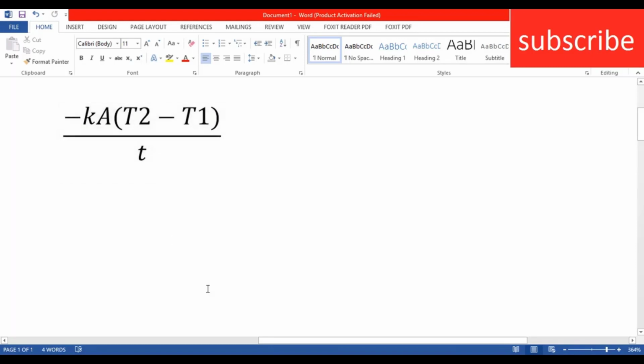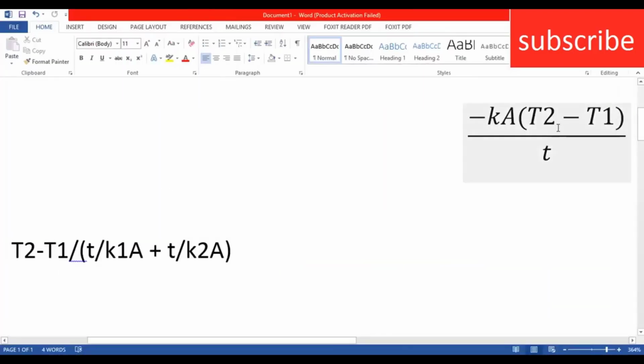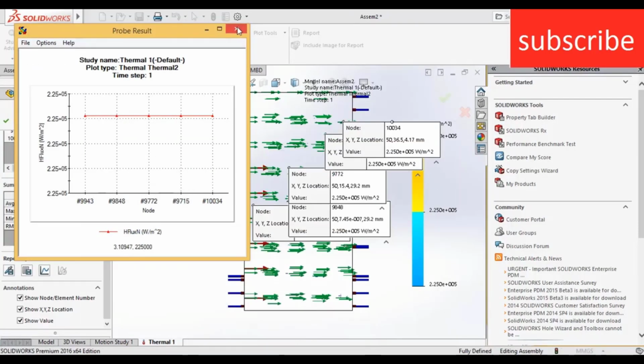If you put in the values of all the things we calculate, for example, K is 50, I guess, the material value is 50, and area is 100 by 100 mm. So you need to convert the units. Either you convert A into meters, so that T in meters you can calculate it, because our units here are in meter square. So convert all these units into meters, and we get the value of Q.